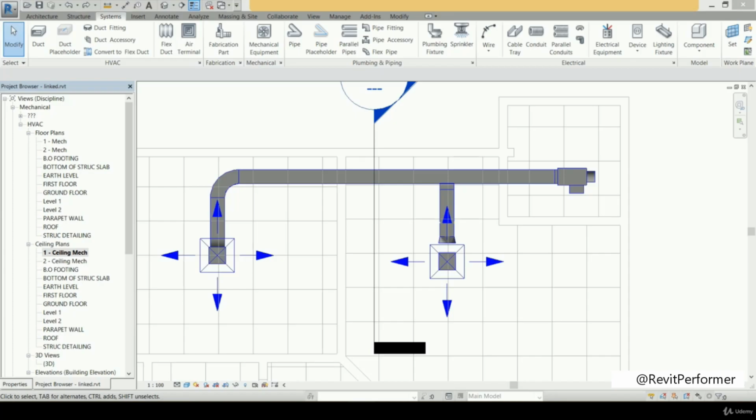This is because the temperature outside the building or at the roof will be larger in the summer season, so the heat exchanging process between the duct and the outside air will be larger than if the duct lays inside the building, where the temperature will be lower, and then the heat exchange will be less than the exterior heat exchange.